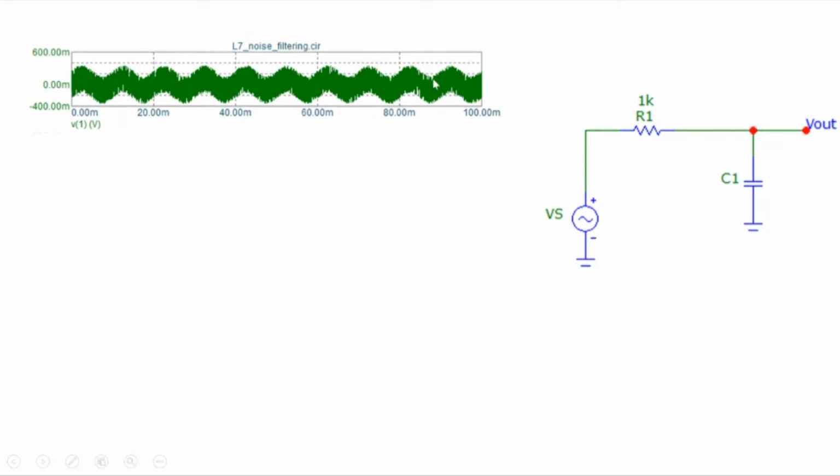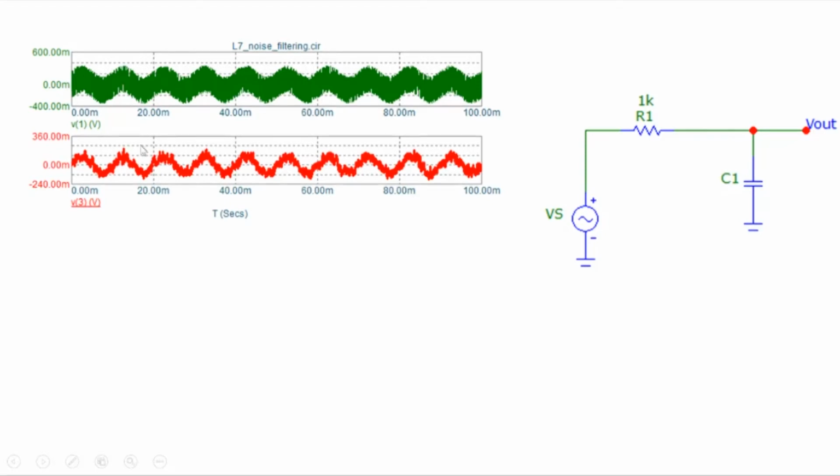Now I can take a very simple circuit that you are familiar with, a simple resistive capacitive circuit, an RC circuit here. I can apply this signal as an input, and then look at the output. Look at what this simple circuit is able to do. It's able to reject noise to a large extent, and now you can see the sinusoid. Even now it's still noisy, but you can see the periodic signal, you can measure its frequency, you could tell maybe what its magnitude is, but you could filter it even better.